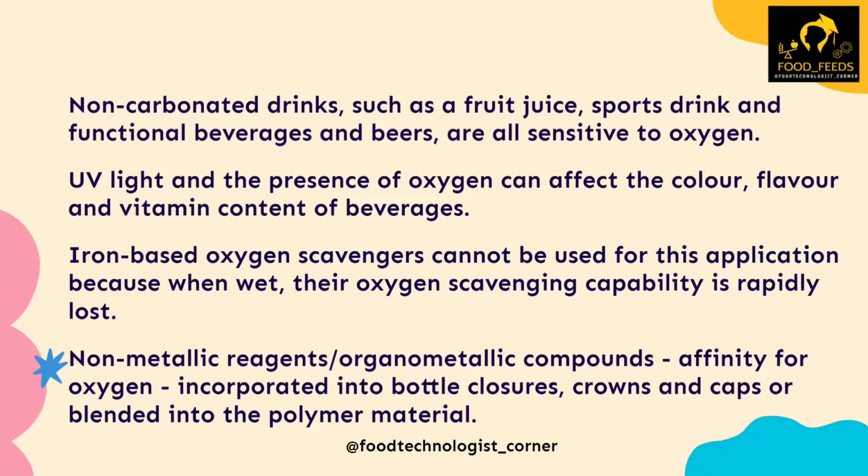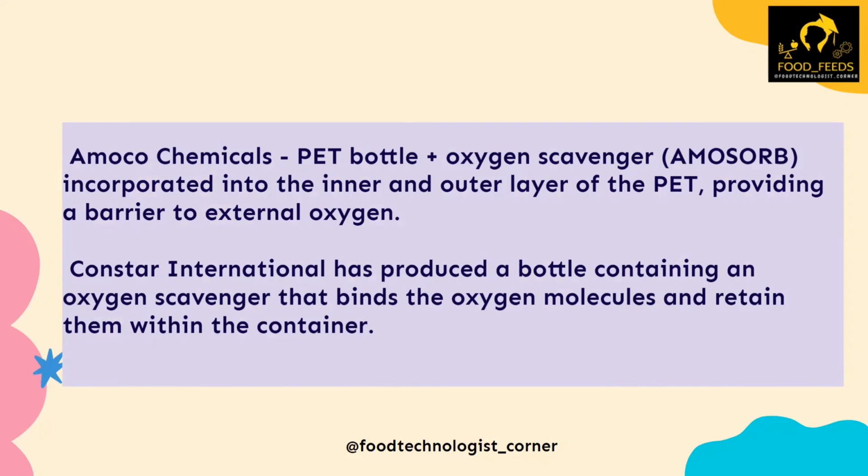Instead, non-metallic reagents or organometallic compounds which have a higher affinity towards oxygen are incorporated into the bottle caps or closures, crowns, and they are blended into polymer material, which will help to scavenge this oxygen. There are different companies which are using these oxygen scavengers in different forms. Amoco Chemicals developed a PET bottle with an oxygen scavenger incorporated in both the inner and outer layer, so that it provides a barrier to external oxygen coming inside the product.